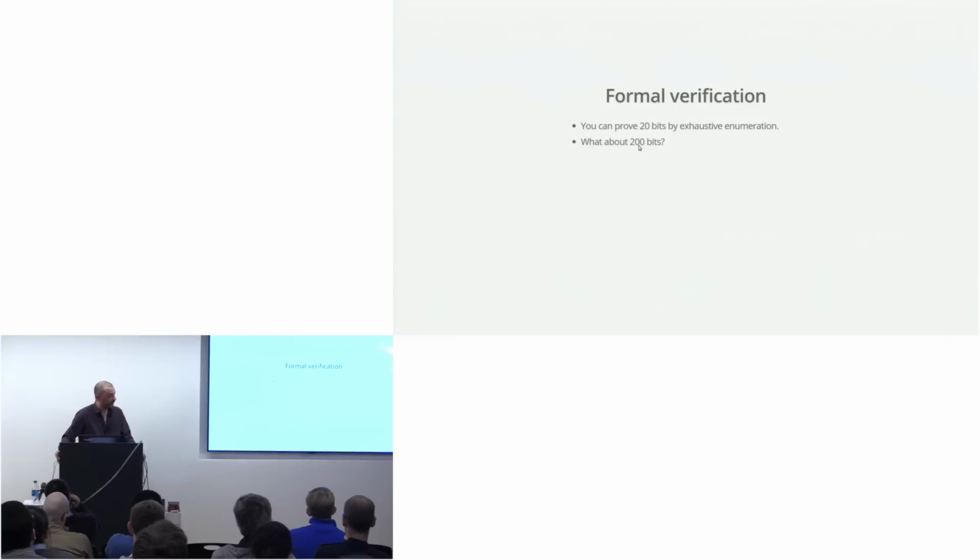Okay, so I thought we'd have a quick detour into the world of formal verification. So let's say you have a 10-bit adder and you want to prove it's right. Now, you think 10-bit adder, why would you do that? Well, it turns out a lot of papers get written about adders, a lot of papers. So you've got a 10-bit adder, 20 bits in total, what's that? 1 million test cases, no problem. Well, if you want to test 200 bits, it just ain't going to happen that way.